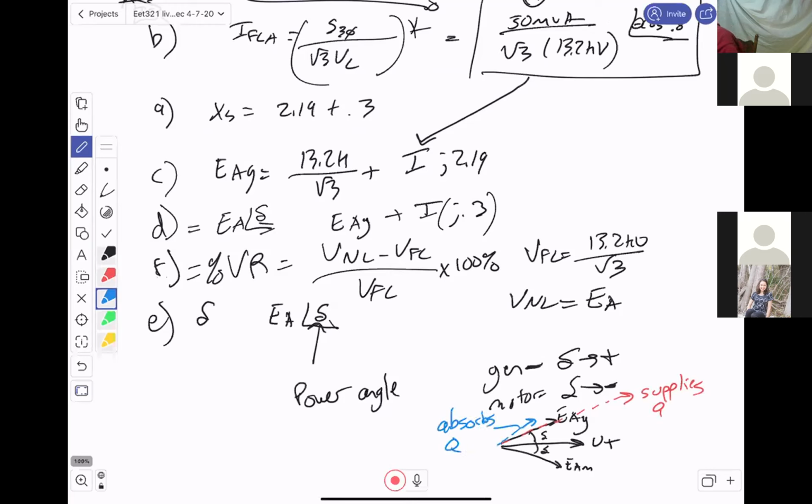So you can just look at a phasor diagram, and it's especially true for generators, because generators have very large X over R ratios. And that's another thing which makes generator protection really challenging, because you have so much fault current available that is not symmetrical. And we'll discuss that more probably next year. You have so much asymmetrical fault current that you have to have special breakers, generator circuit breakers, that can interrupt that.